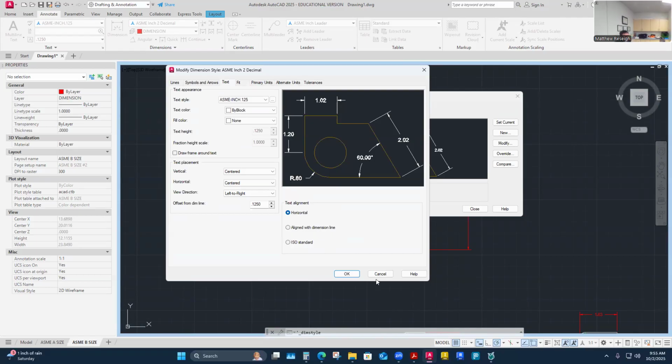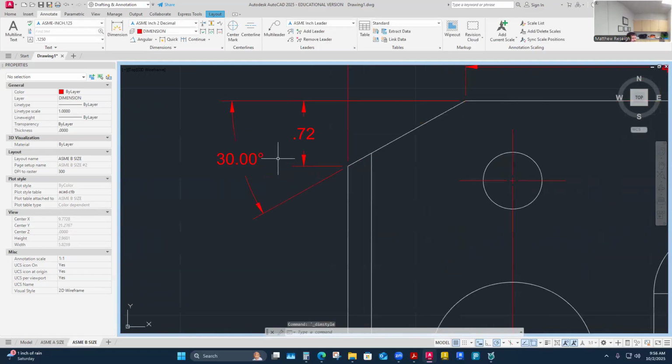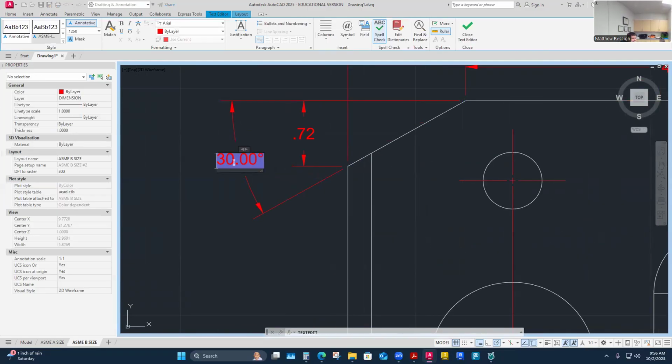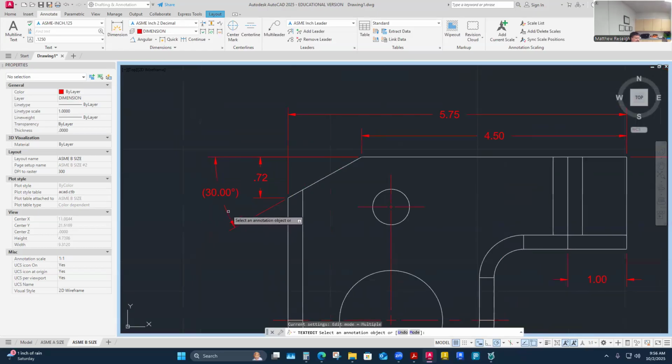I can't say for sure if you've covered that in your chapters. You probably have in your theory book. Essentially, it becomes a dimension in parentheses, though I'm not going to actually do that yet. I should be able to have a dimension style where it applies something like this. This is how a reference dimension will look on your drawing. It'll be in parentheses, which indicates to someone that it is not a critical hold point. That's just for reference information only. It may or may not fall inside this actually.